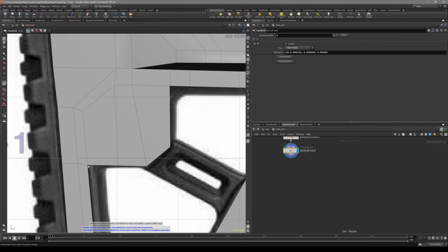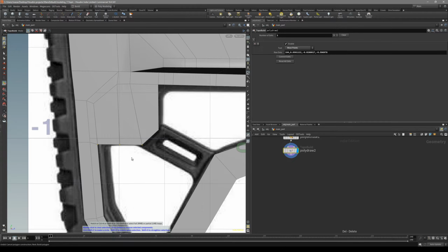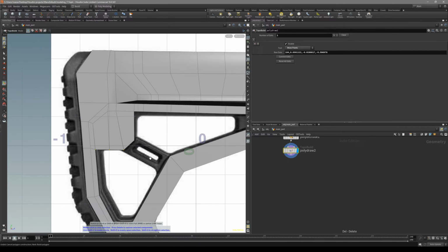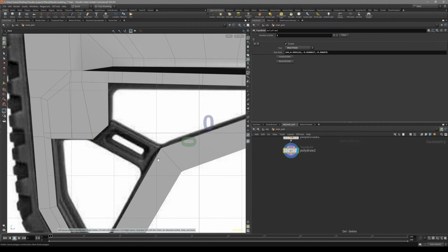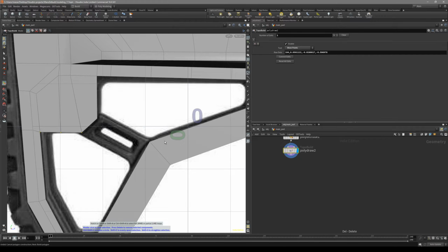We're gonna bevel also these, and let's straighten out these. So select these. So make sure that these points are where we want them to be. Let's say here and here. Select them, and S, Shift S, like that. So for the bridging, we're probably gonna have to extrude it again and then bridge them, but that's a little later.